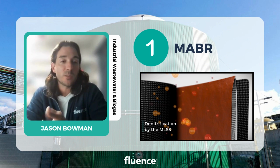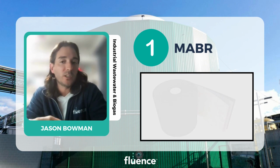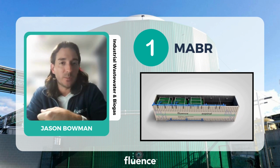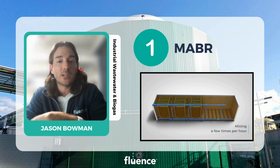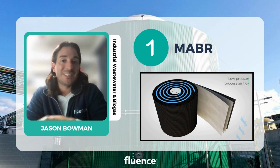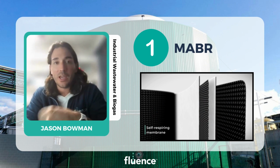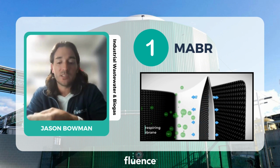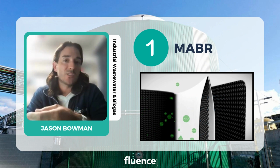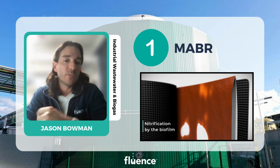So these MABR units are placed inside of a reactor where the bulk liquid condition is actually anoxic. So as the biofilm begins to oxidize ammonia to nitrate, the nitrate is combined with the COD or the BOD in the bulk liquid where simultaneous denitrification occurs. So this is where we get our low energy consumption from. Only air goes to the nitrification process. Since this is a passive aeration process, it's much easier to diffuse oxygen at much lower pressure, much lower energy, to introduce oxygen directly to the biofilm.